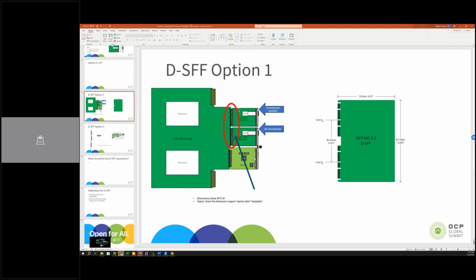We will have a riser on top of the small form factor, and the riser provides flexibility so that we can leverage the riser concept to change the design, change the CEM slot to another OCP small form factor slot, and have a stacked small form factor design, so that we can have a portable connector to connect these two small form factors together to have 32 lanes.